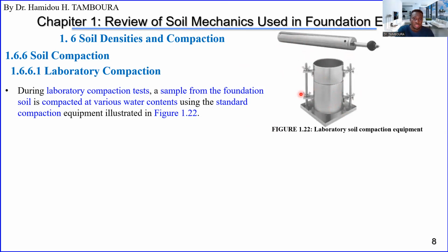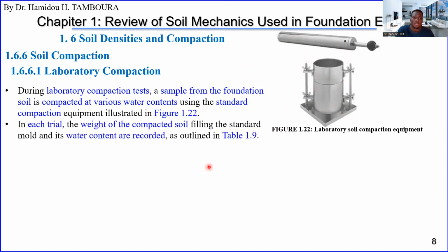Each trial, because you will do several tests as stated here, for each sample, the weight of compacted soil filling the standard mold and the water content are recorded.